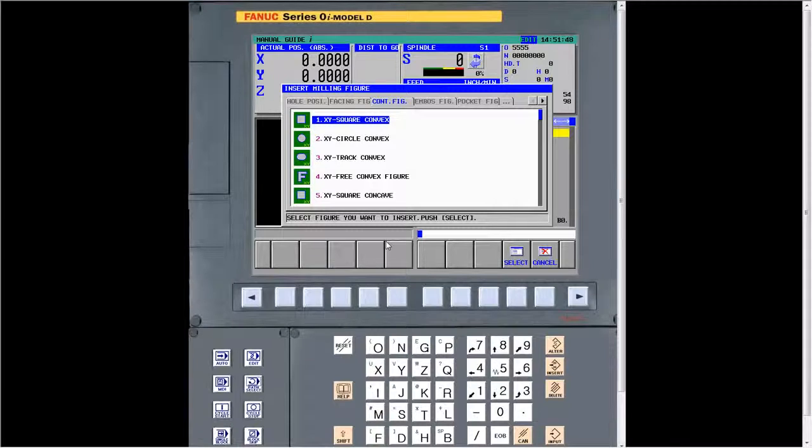A lot of times, with multitasking machines that are truly 5-axis, it will do 4. You can't do 5 within Manual Guide I. But the 4 for what you're talking about would be enough to do the chamfer, as long as the configuration is standard. But yes, it could do that. We just have to set it up correctly.